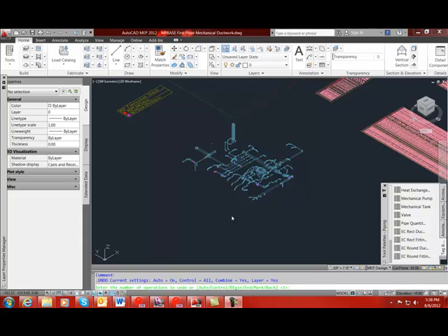In following the steps in the previous videos, we applied the most common specification to all of the ductwork in the drawing. Now to apply the correct specifications to the remaining ductwork, you go through the system and select all fittings and duct that will use the same specification and use the duct fabrication tool on the ribbon to apply the proper specification. This allows you to apply the specifications all at once instead of going through each one individually.